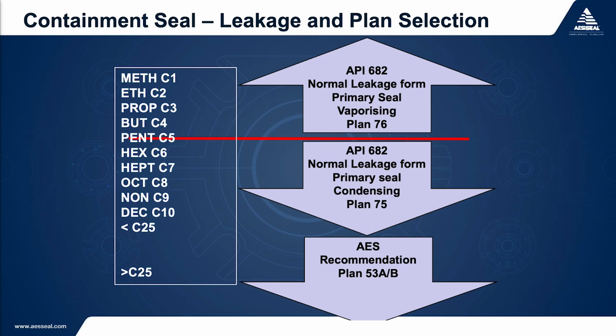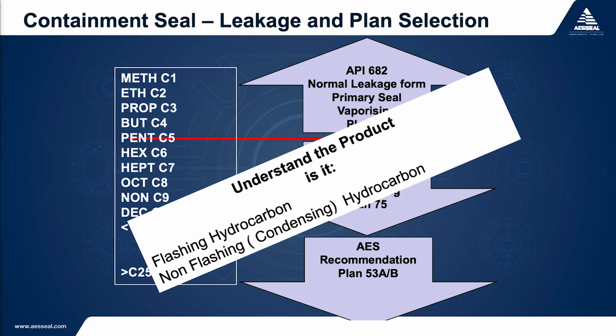One thing often ignored is the summer and winter ambient temperatures. Some leakage could exhibit as a vapour in the summer months, but form a liquid in the colder winter months. The key to selection is really understanding the process and how it behaves.